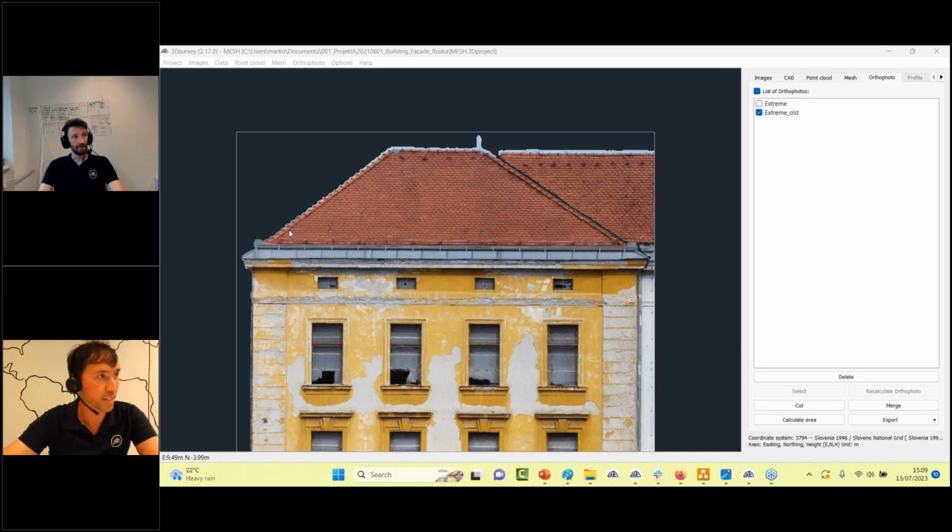Okay. Mattia, would you like to add something before we close this webinar? Maybe just something like a warning. If you install version 2.17 and run into some problems with bundle adjustment or dense reconstruction, please make sure you update your NVIDIA graphic card drivers. It's very important because we did some upgrades in the environment, and the older versions of the environment are now deprecated. So you need the newer drivers to work properly.